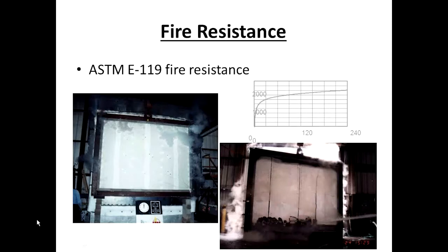And those pressures are significant. I'm going to be walking through some partitions in the next few slides. But for example, at 1 hour, that technician is hitting the wall for 1 minute with 25 psi water. At 4 hours, the pressure pumps up to 45 psi. The time goes to 5 minutes. So he's playing that water back and forth for 5 minutes. If you ever want to see a gypsum guy get sweaty palms, you have him stand and watch that test, because it is horrific.